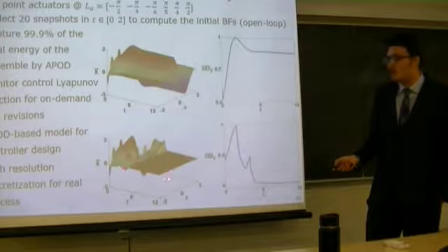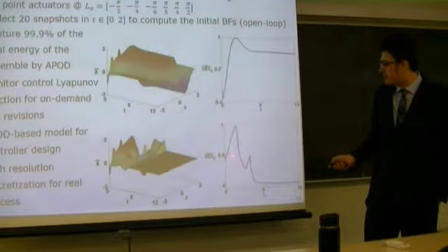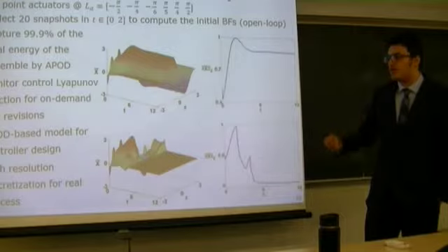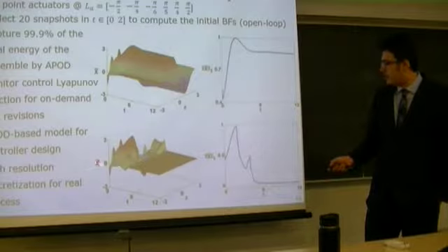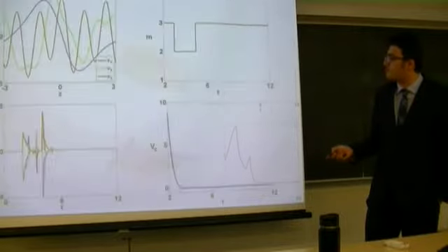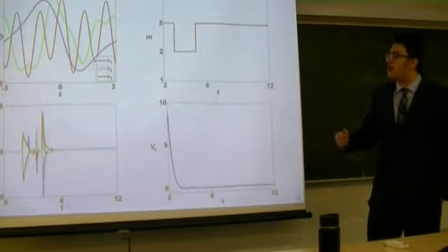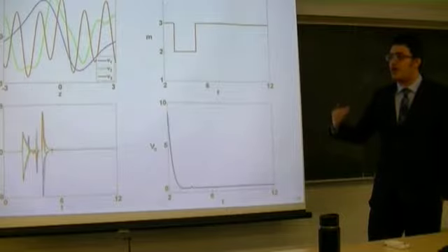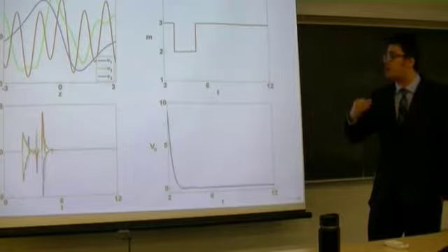And this figure shows the closed loop dynamics. From 0 to 2, the control is not active until this point, and then the control is activated, since in this open loop period we are collecting the snapshots to initialize the control structure. And as you can see, it works perfectly. The spatiotemporal profile goes to 0, which was the desired result for the wave motion suppression. This figure shows the initial set of basis functions, which are derived based on offline proper orthogonal decomposition during that 2 seconds of open loop process operation.